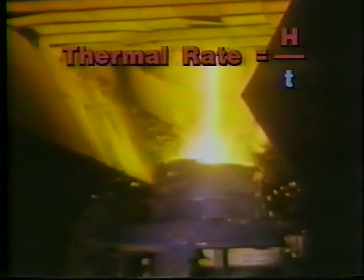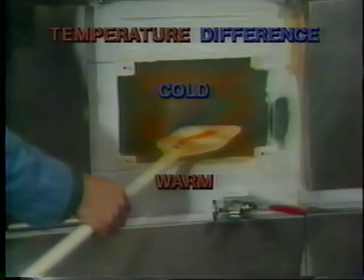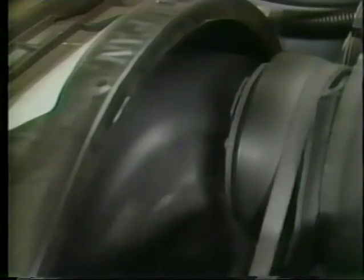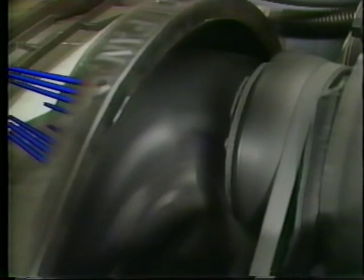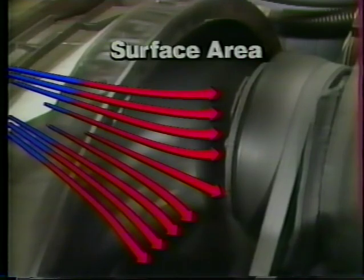Whether we're trying to generate heat or take it away, it's moved from one place to another in thermal systems. How fast the energy moves, or the rate of heat flow, is not quite as simple because there are 4 conditions. Temperature difference acts like force to actually move the heat. Surface area makes it easier for the heat to transfer. Thickness is how far it has to go.